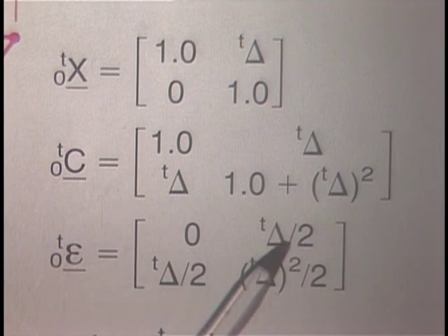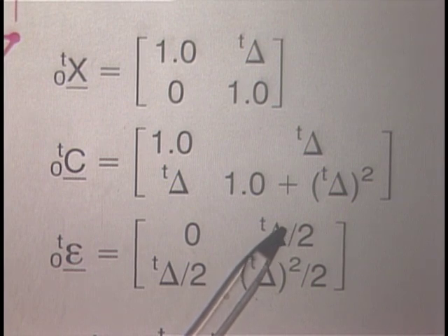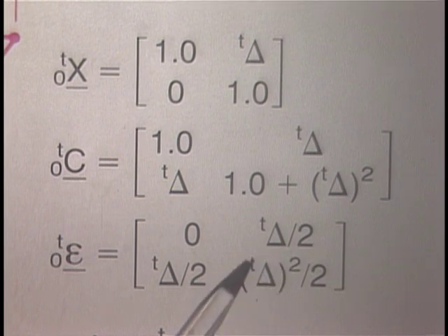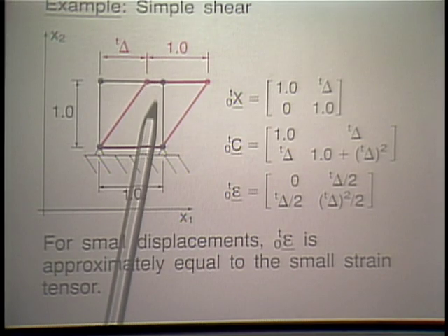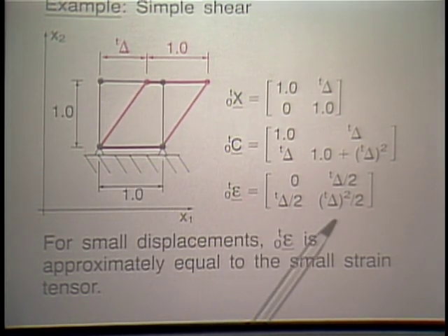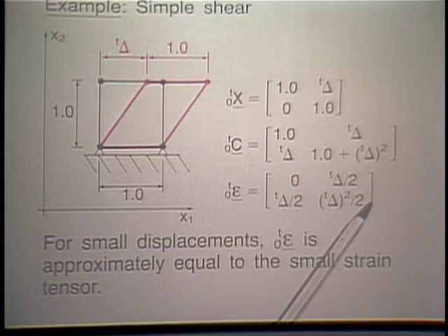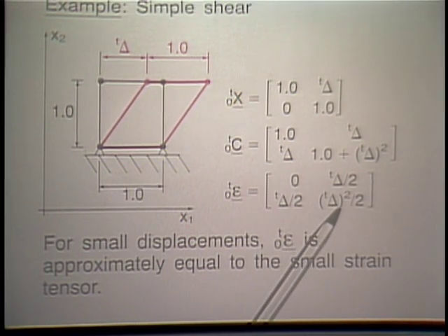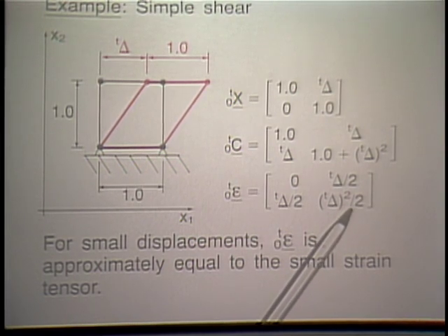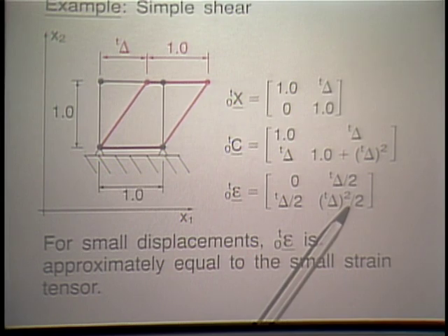Notice that here we have now shearing components, and notice also one very interesting phenomenon, a component appearing here. This is an interesting component because it is really a normal strain component in this direction. In other words, an epsilon 2 component that is non-zero in this particular case. In a materially nonlinear only formulation, where we only include infinitesimal displacements, in other words, this part, of course, would be 0.